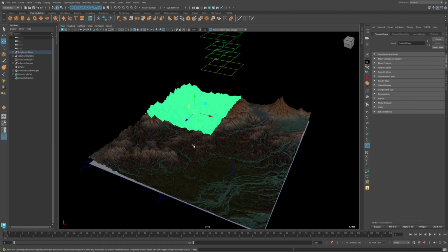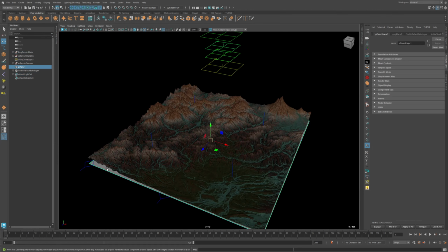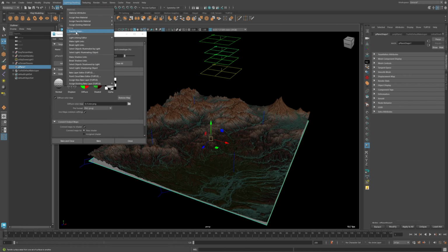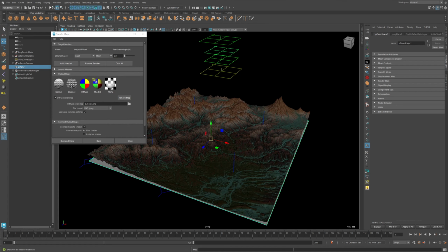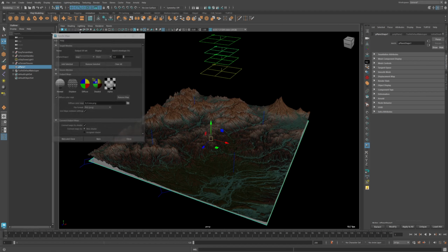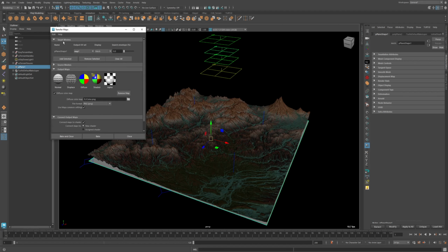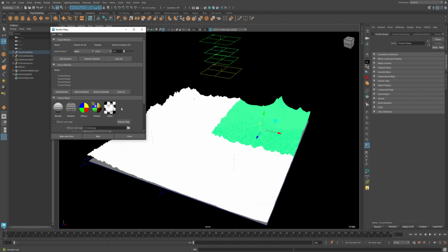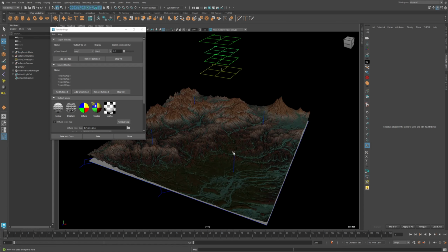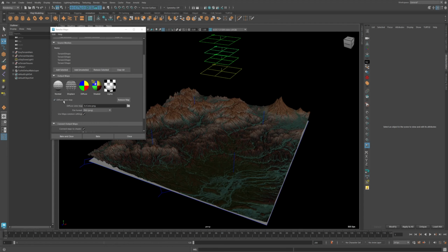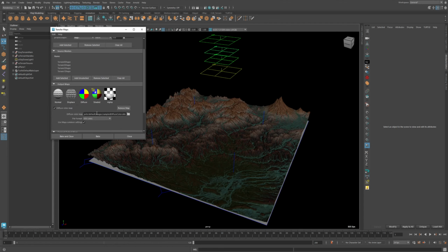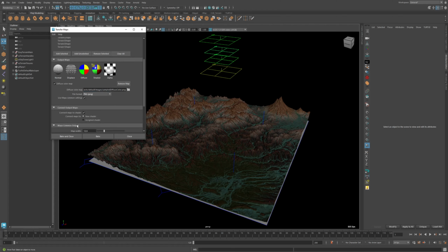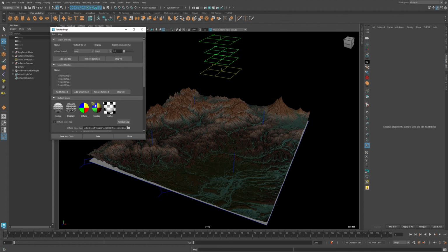And for the albedo, you can also do the same thing but using transfer map. So for example, let's open Transfer Map, Lighting and Shading, Transfer Map. Make sure to set it to rendering first. Here our target mesh is going to be this plane, and our source mesh is going to be all of these train surfaces. And now over here we want the diffuse. If you don't have it here, just click on the diffuse. It is going to create a diffuse color map for you. Set the file format, and here you can change the resolution. After that, just hit bake.